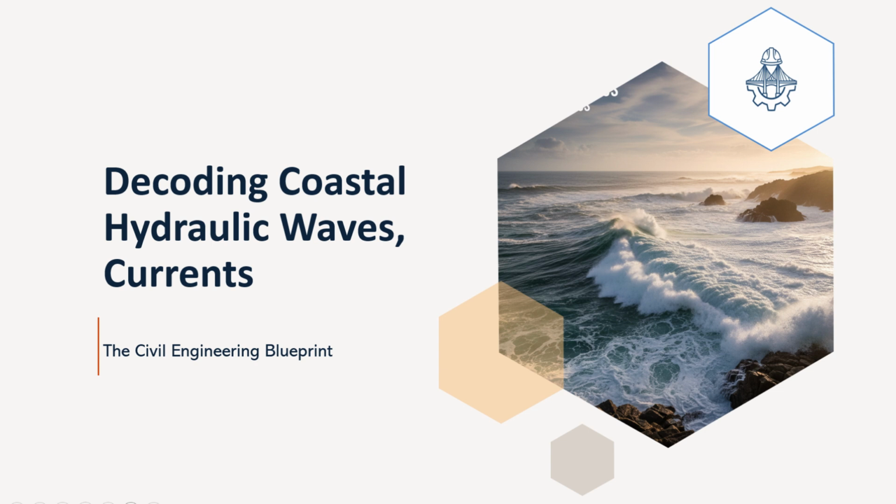A widely used approximation, originally suggested by McCowan in 1894 based on solitary wave theory, is that a wave breaks when its height Hb reaches approximately 0.78 times the local water depth db at the breaking point, Hb equals 0.78 db.